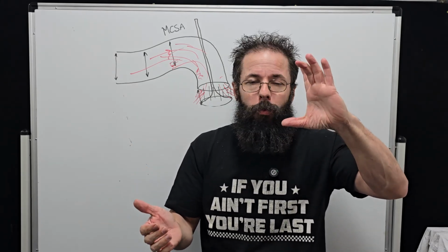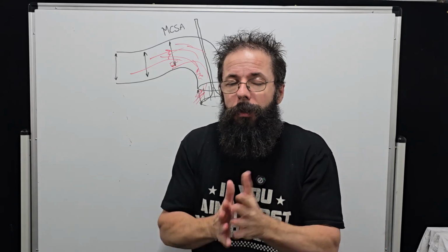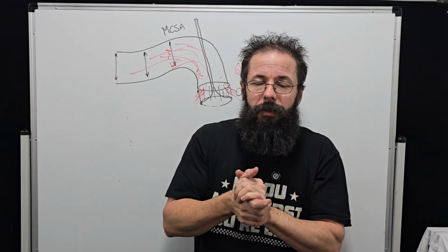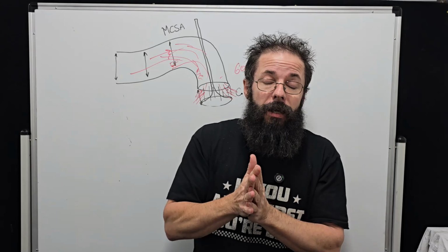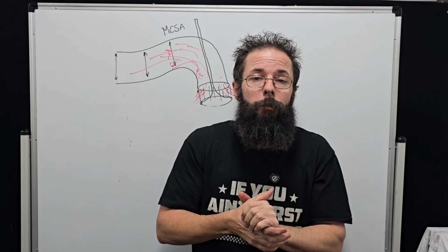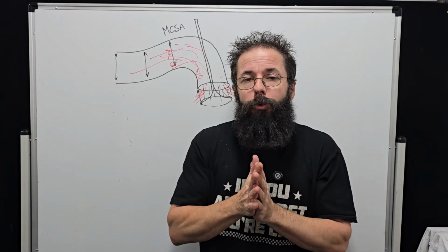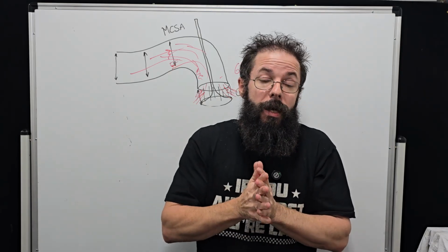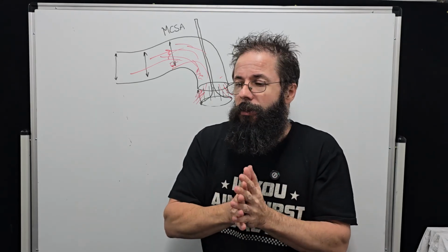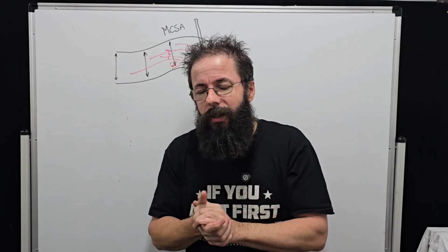If the window is 50% bigger than the MCA, then the window is too big or the MCA is too small. So we've got to use a little bit of common sense. But I tend to target the twin cam stuff as low as 600 feet per second at our minimal cross-sectional area, some even lower, especially with the turbo stuff. The higher the boost goes up, generally the less they want to flow at those high velocity rates. So as we increase density, we increase port drag. So there's a little shift we'll see there as far as the calculation goes.